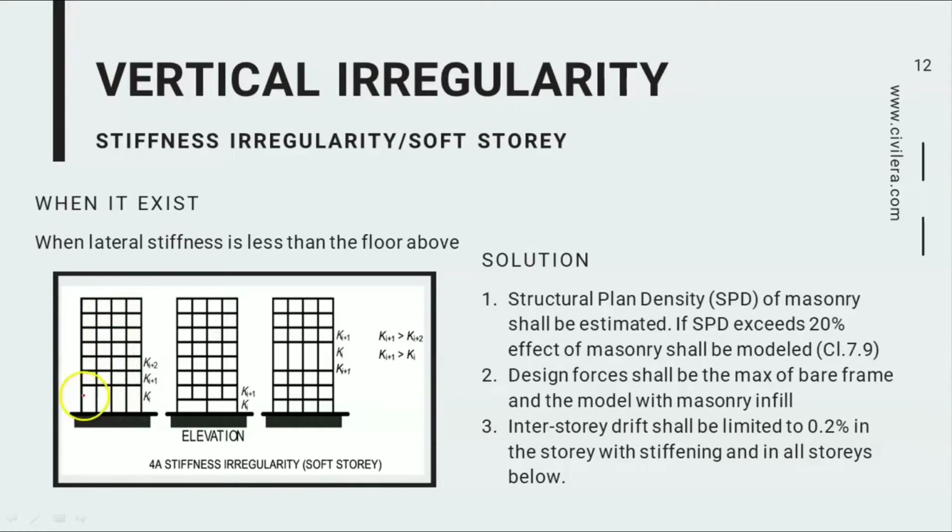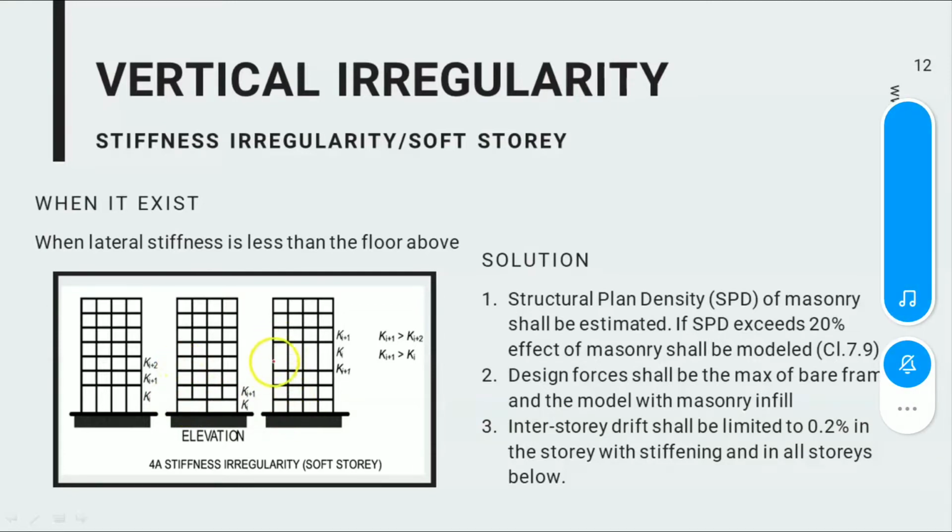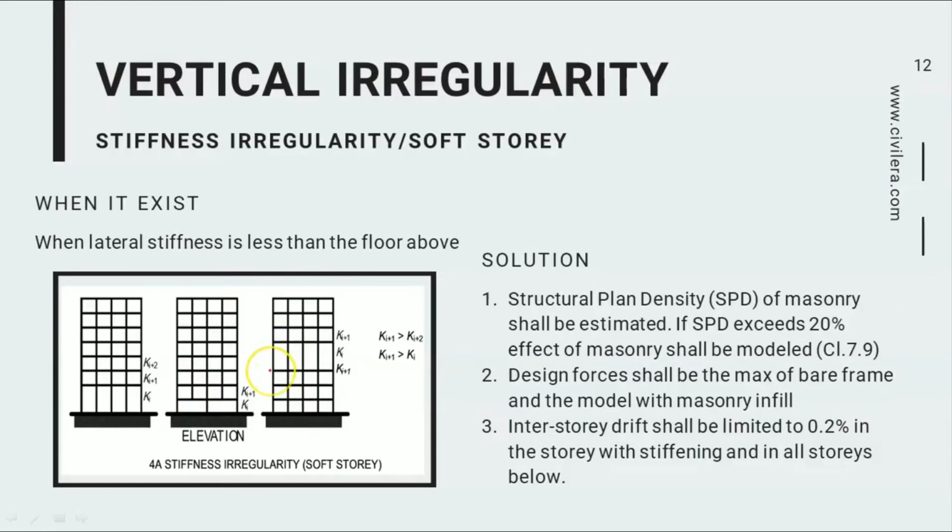This means that the stiffness is less. Here you could also have something like a stilt floor in the lower floor and walls in the upper levels. Here we have floating columns as well. Here there is an intermediate story where you have larger length, lesser stiffness. So all this creates stiffness irregularity or soft story in your building. So there are conditions here. So this represents the irregularity.